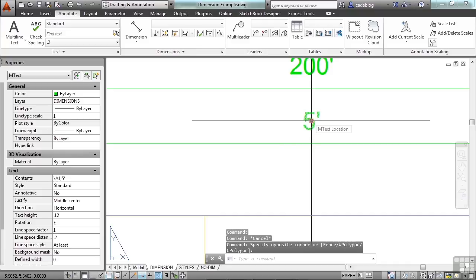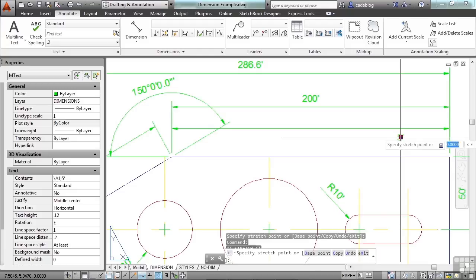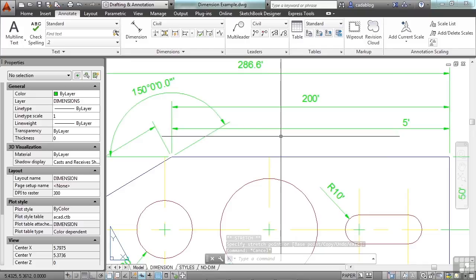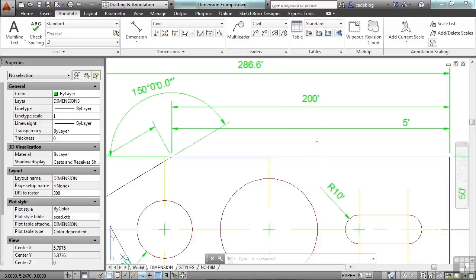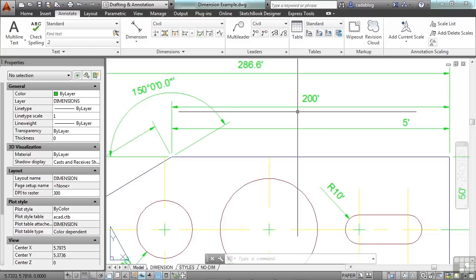Now the nice thing about this is that I can do whatever I want to this dimension, and it's very easy to edit it. But as you saw before, there were tons of ways and methods and tools available to us to change the display settings of our dimension. You really don't gain anything by doing this. So this is an old setting in a way when we didn't have as many controls visually of styles for our dimensions. So people would do this to be able to make them look the way they need to, but you lose control. You lose quick control.